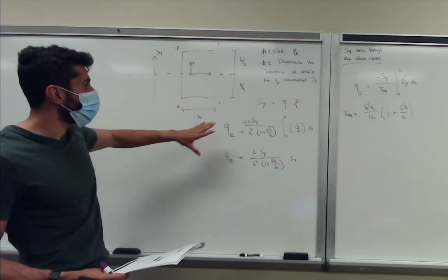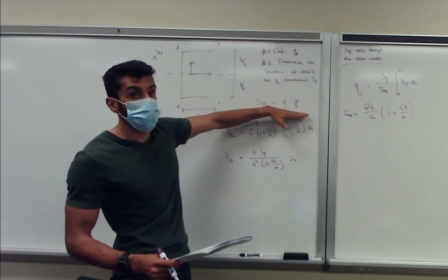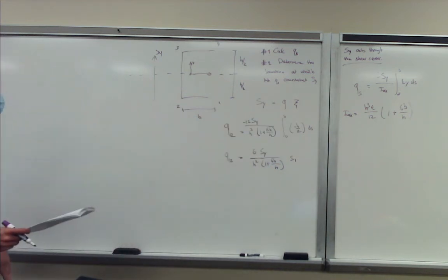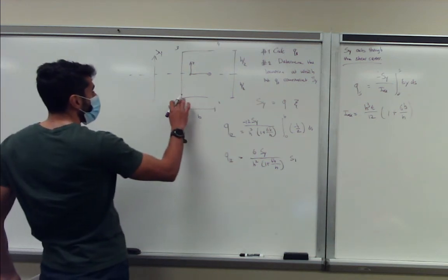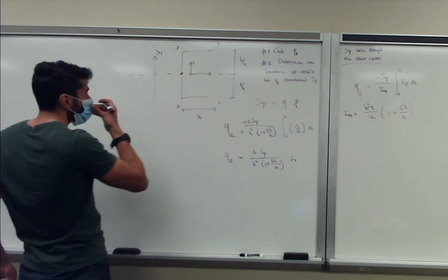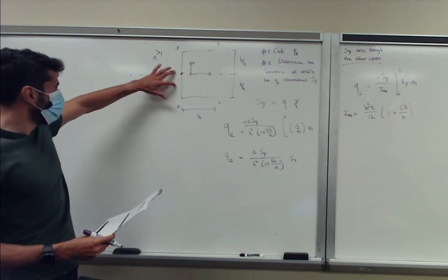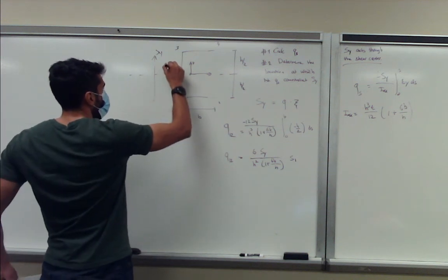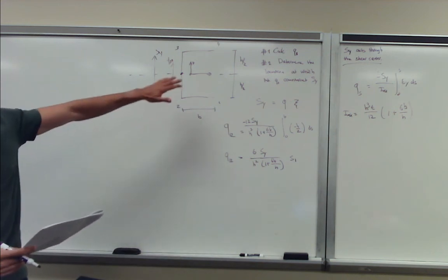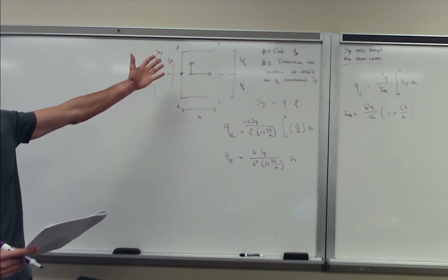The reason is that we basically want to do a moment equivalence equation, so we can choose a location, take the moments around it, and choose that as our coordinate system. For example, if we take point 3 in the middle, then shear flow Q23 will go through our moment axis, so that contribution will drop out.